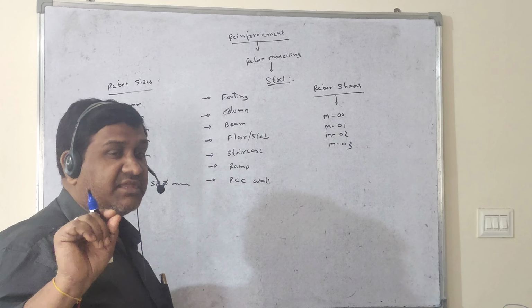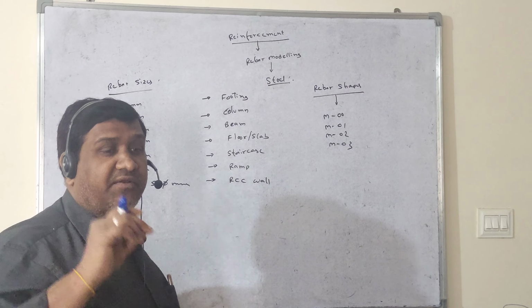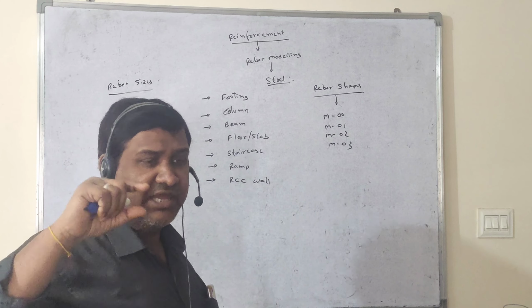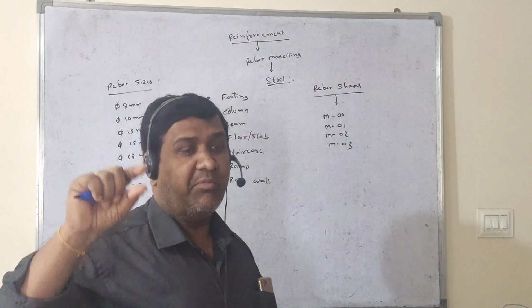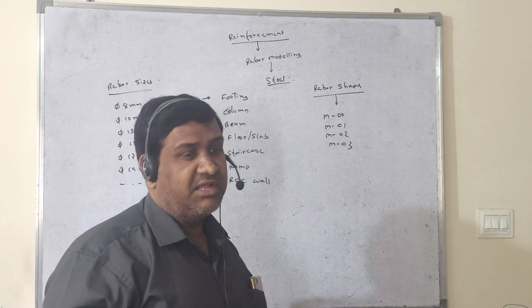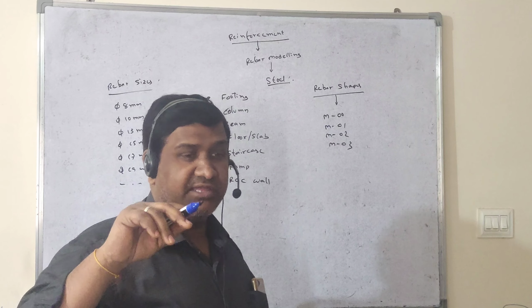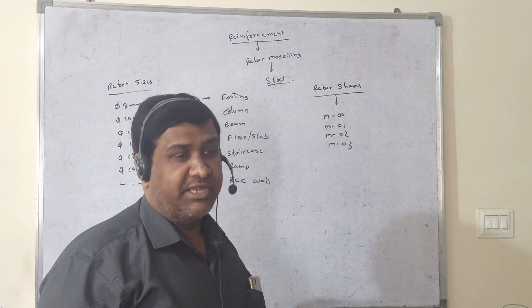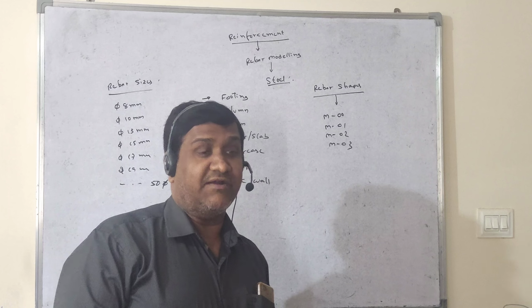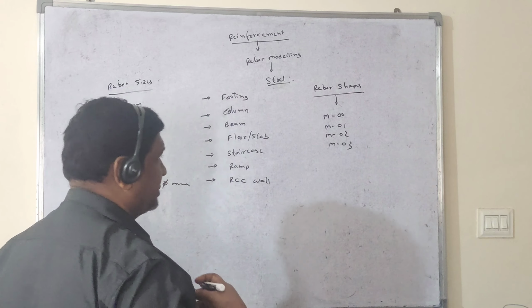You have to choose the size, then the rebar shape, and based on the shape you provide the rebar for each and every component. Here, the rebar model is also shown with solid objects, and you can check the length and the bending hooks. What is the radius of the hook, what is the bending moment radius, everything. The properties come automatically after making the model of the rebar.